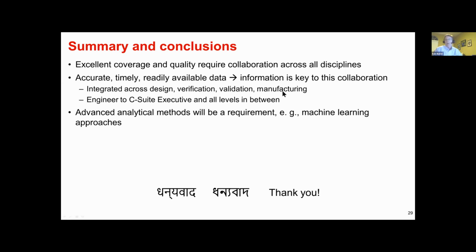Because wafer variability with 12-inch wafers, and in our case very small die size, within-wafer variance can be enormous, so we're looking for intelligent ways to do that. That's just one example where you can apply machine learning techniques to enhance the overall test operation.